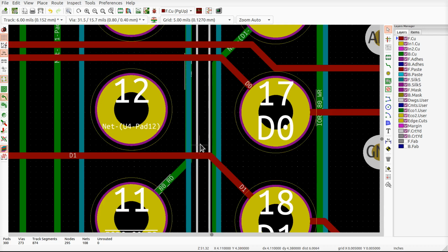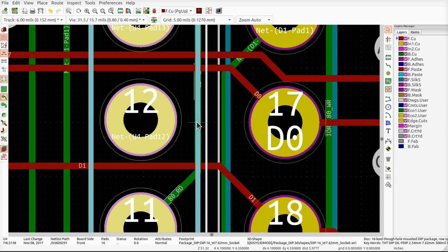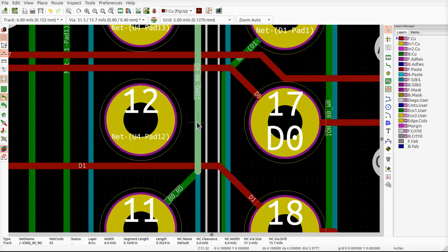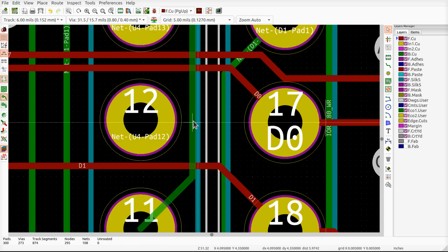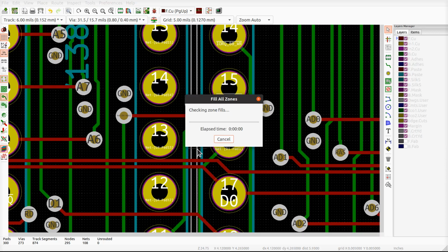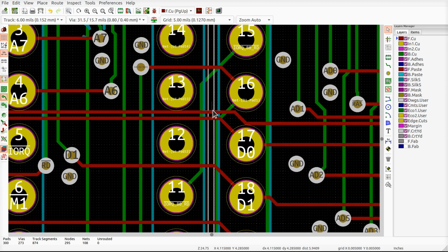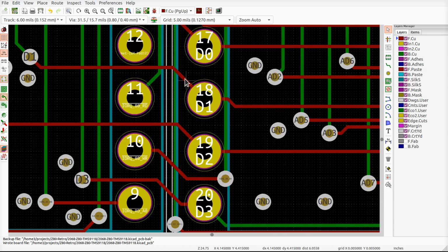All right. What's this one? That's the read line. Now, if any of these signals ends up getting on that interrupt line, it turns out that if that interrupt line is just being used to poll the frame, if there's some noise on it, it's not the end of the world. But if that's an interrupt line that goes to the Z80, you might have a problem.